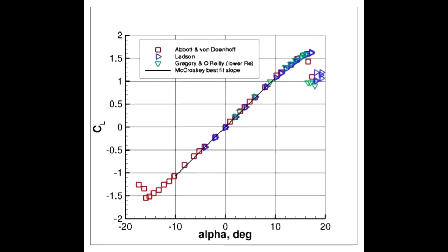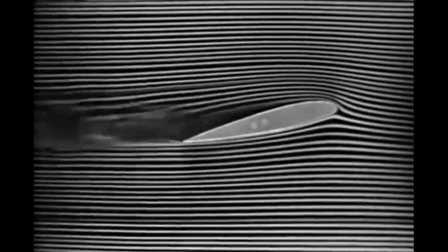So typically what we obtain is as follows. Here we have the lift coefficient. Each airfoil has a graph of this type. Typically the lift increases linearly with increasing angle of attack, but at a certain critical angle of attack we obtain what is called the stall. So if we increase the angle of attack further, we will lose lift.